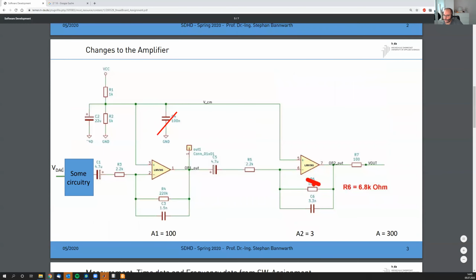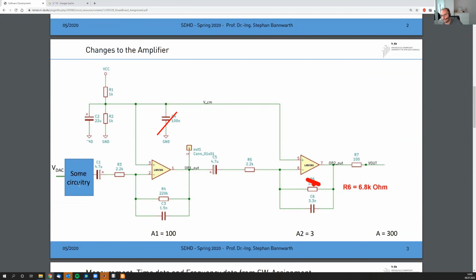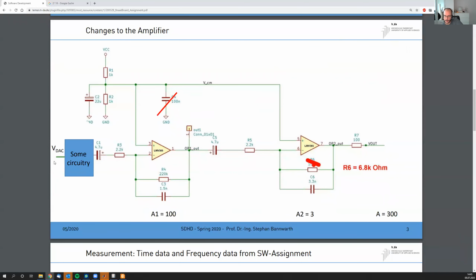And once you have that, you can bring in your voltage divider here, do the measurement again, and check if the voltage going in is approximately what you expect for the circuitry here. Yeah, that could be one way to do it.